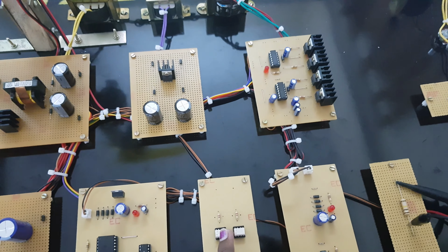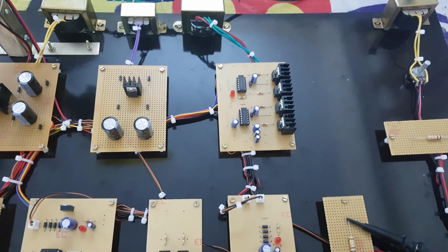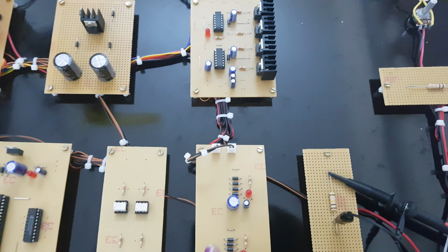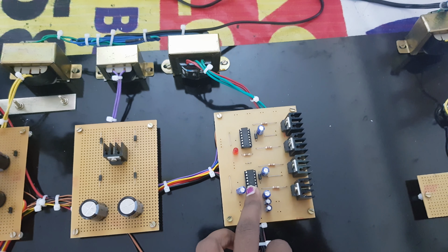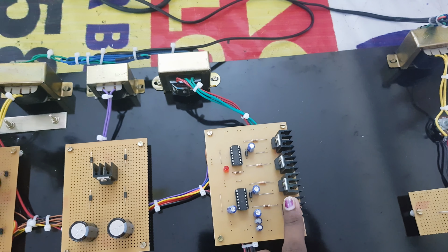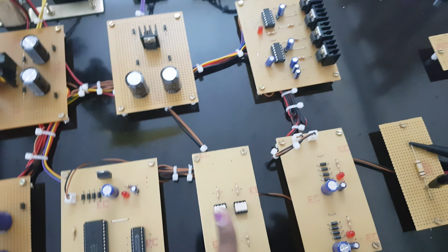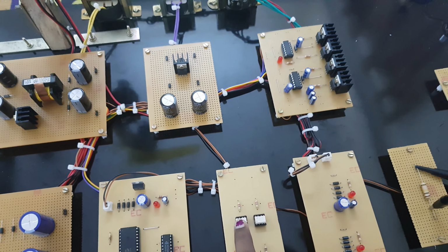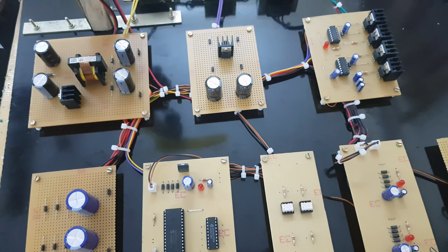So this is an optocoupler, which is an 8-pin opto. This opto is used to trigger these two particular switches over here, and this is a supply board for the opto, and this is the gate driver, which is a FAN7392N, which triggers two switches over here. This is our MOSFET switches with a heat sink, and the purpose of the opto is to deliver the 12 volt to the MOSFET. The MOSFET switches conduct only when they receive 12 volt. In order to reach the 12 volt, we are using an opto for the particular switches over here, because they are separate switches, so separate optos are over here.